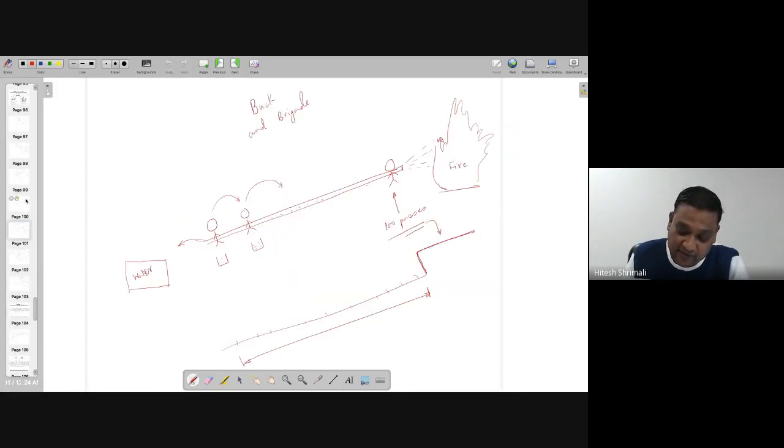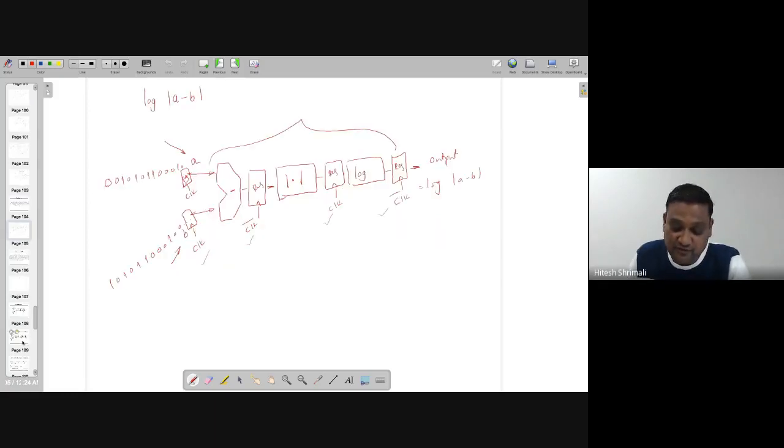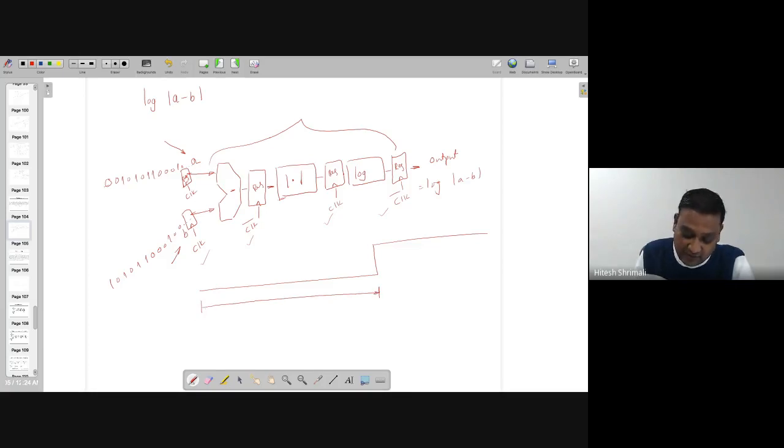The output was coming after 100 passes. So this also requires some sort of clocks, and thereafter the output is available. It's not a delay, I would say, but it's also kind of a delay. After this particular time the output is continuous, meaning till the time these clocks are passing, the output is not coming. That is known as the latency.